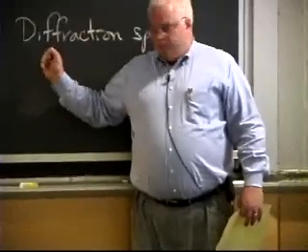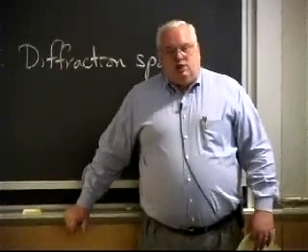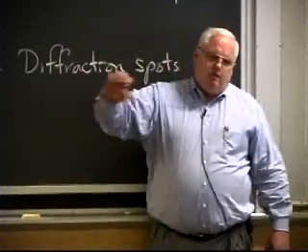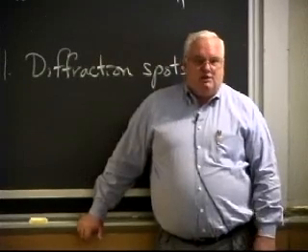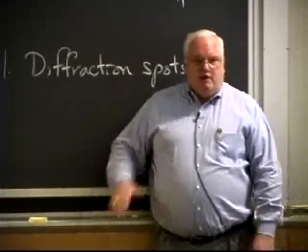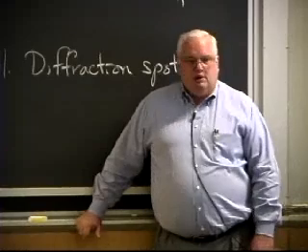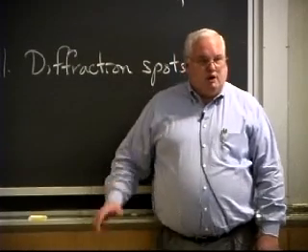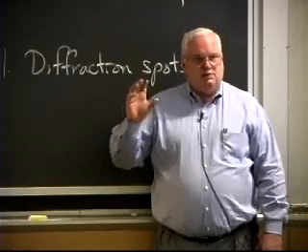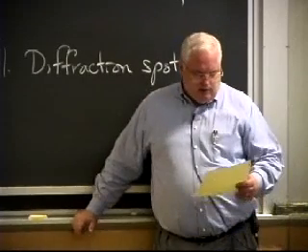The problem with the TEM00 mode is an axial flow laser, like that Hitachi laser, that can put out 5 kilowatts in the multi-mode, where you have lots of different diffraction spots, can only put out about 2 kilowatts in the Gaussian mode, just because it has to do with turbulence in the gas and non-uniformities and densities of the gas as it heats up.